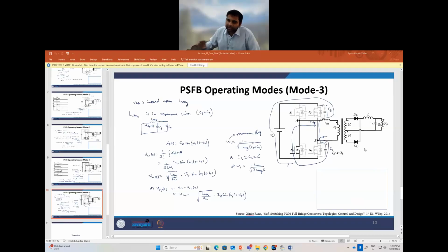So either do the simulation in a Spice simulator, LTspice or PSpice, but then you have to see how you put the closed loop control, or do it in hardware and see whether you are getting the THD properly or not.